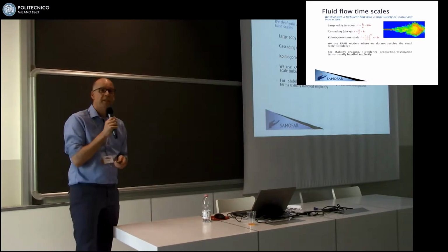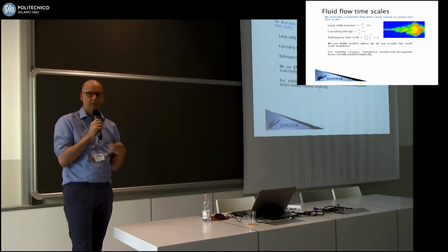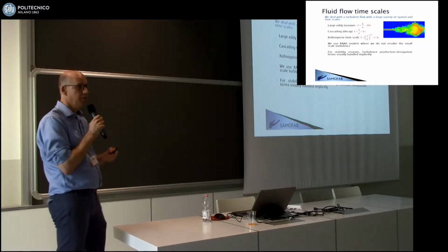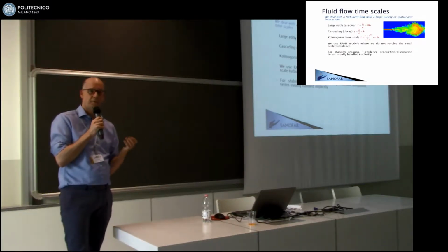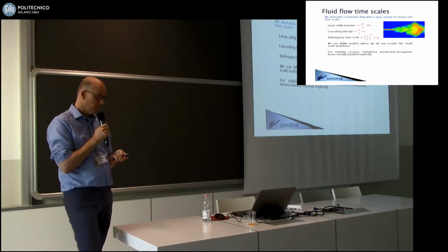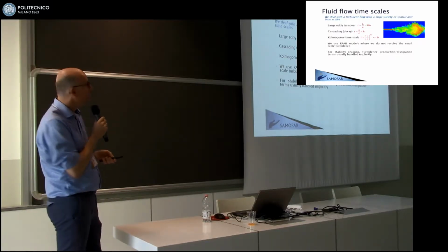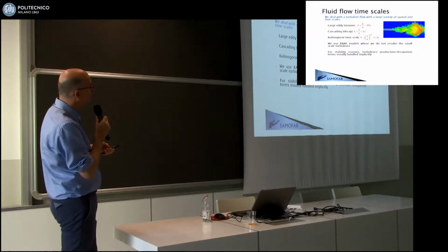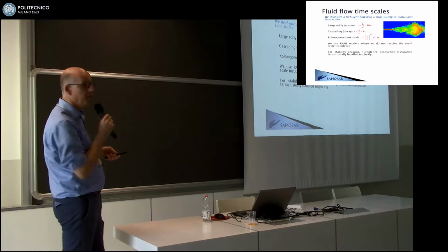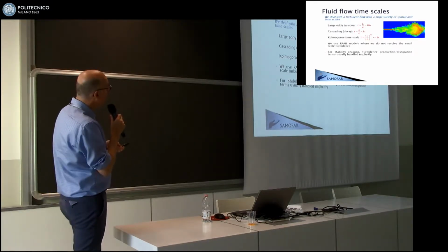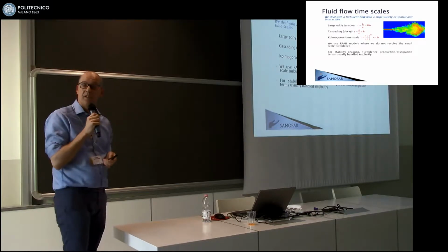Again, here also something about the timescales that are relevant in the problem. Now, it's very turbulent flow, so there's a whole range of spatial and timescales in the system. Let me just only deal with timescales here. The largest timescale in the problem is the large eddy turnover. So essentially, it's the time to move from your inlet towards your outlet, something like that. It could be of the order of about 10 seconds in an MSFR.